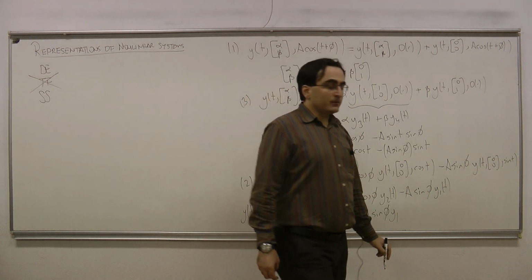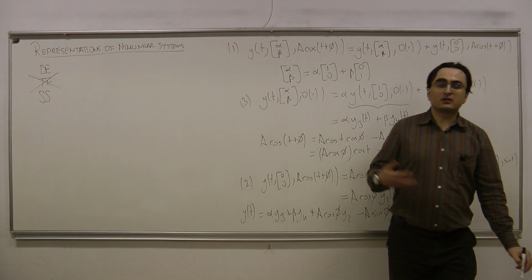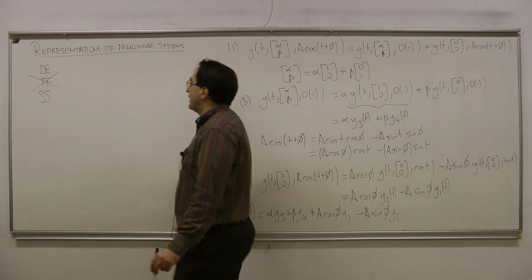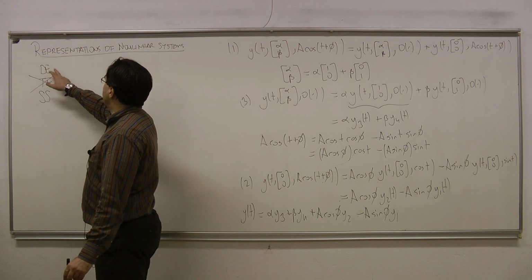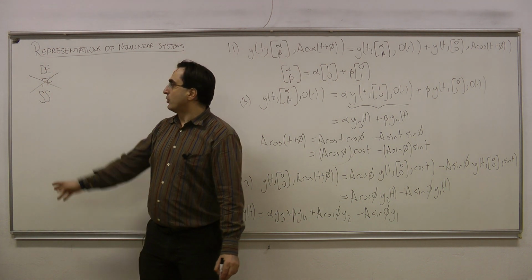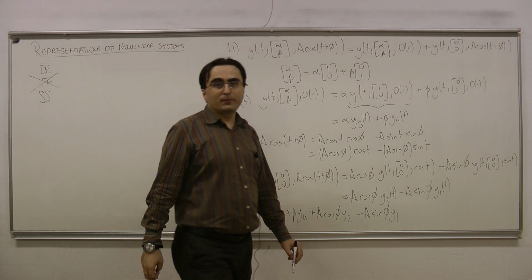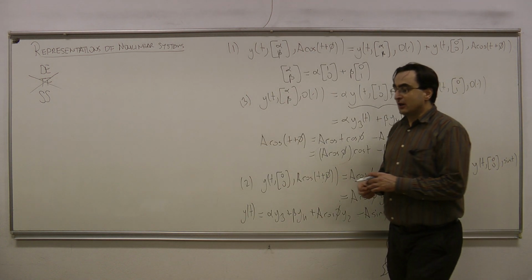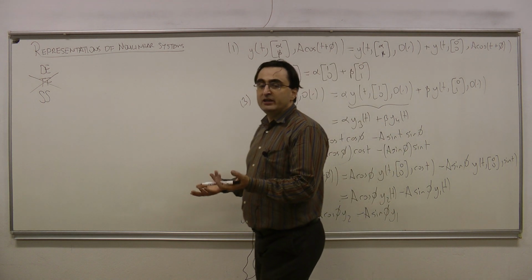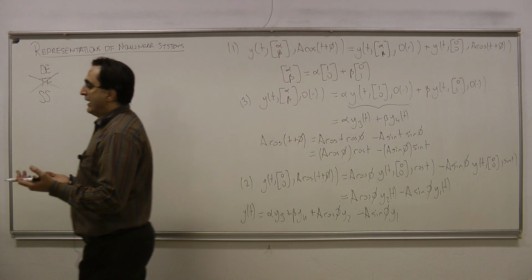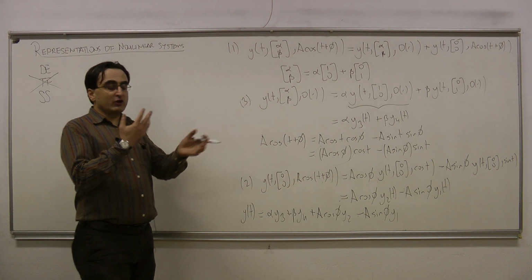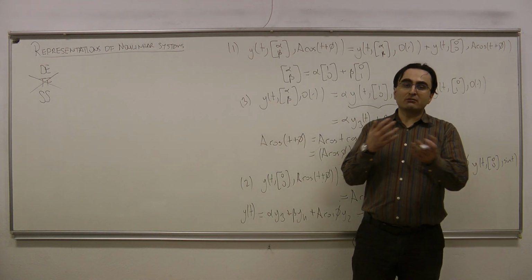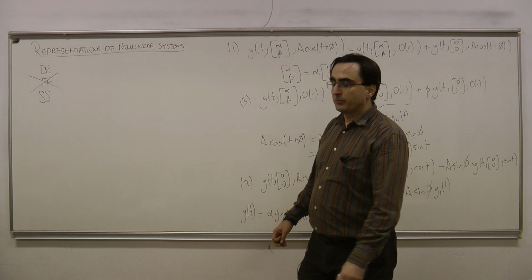You know that a transfer function representation is nothing but a Laplace domain representation, and it is obtained by taking the Laplace transform of a differential equation or Laplace transform of a state space equation. Okay? So in general, a Laplace transform is a linear function. Okay? And it can be interchanged with other linear operators, but Laplace transform can never be interchanged with nonlinear operators.